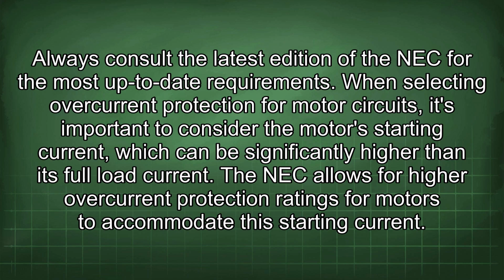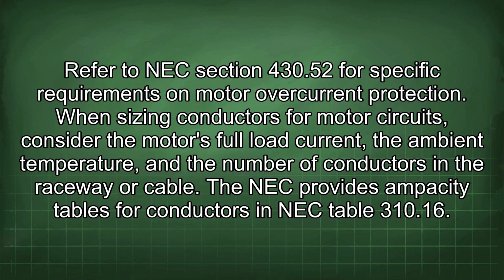When selecting overcurrent protection for motor circuits, it's important to consider the motor's starting current, which can be significantly higher than its full load current. The NEC allows for higher overcurrent protection ratings for motors to accommodate this starting current. Refer to NEC section 430.52 for specific requirements on motor overcurrent protection.